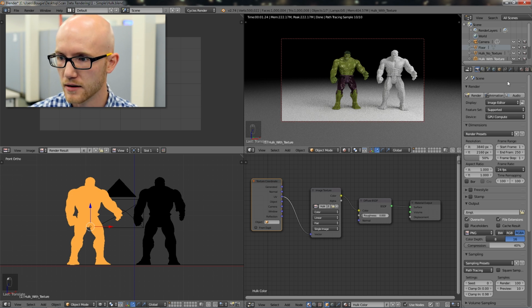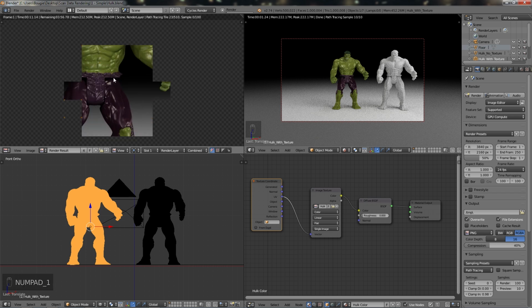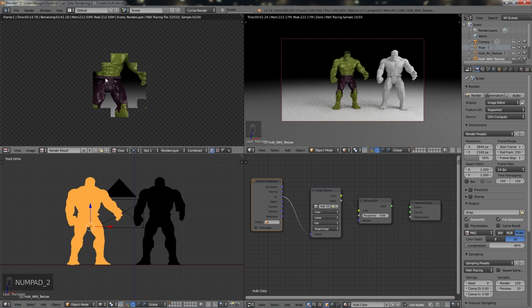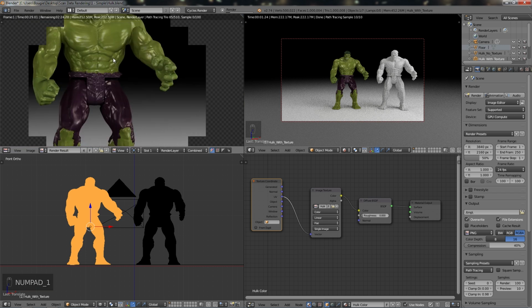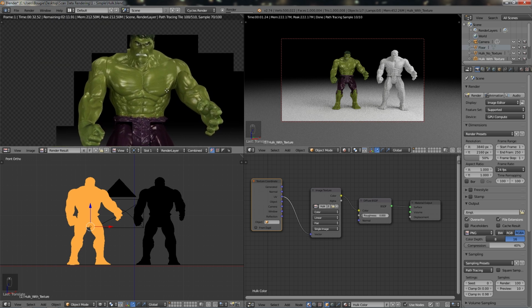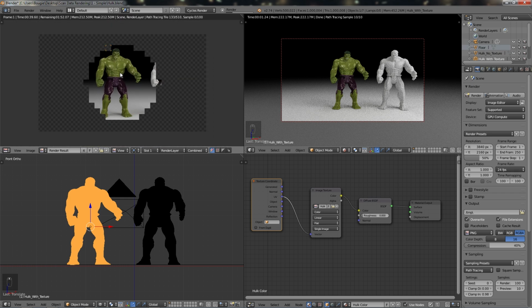So if I'm over here on the right-hand side and I click this little camera button, if I click render, it's going to use my current rendering settings, and it's going to make a static 2D rendering of my 3D image. And I can press 1 to zoom in all the way. Pressing 2 on the number pad puts it at 50%. You can also just scroll in and out. If you scroll too far, it's just like any other JPEG image where it'll start showing the pixels. So 1 is the full-size view. I can click and hold my center mouse wheel and pan around to look at what this is going to look like. And if I hit escape, it will stop my render.